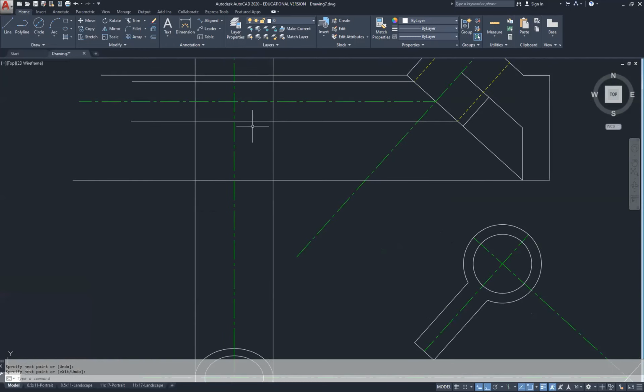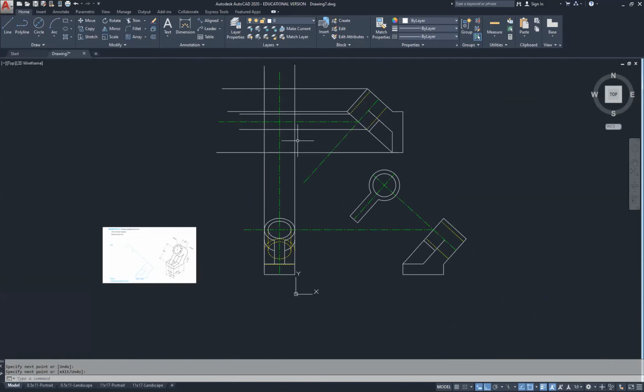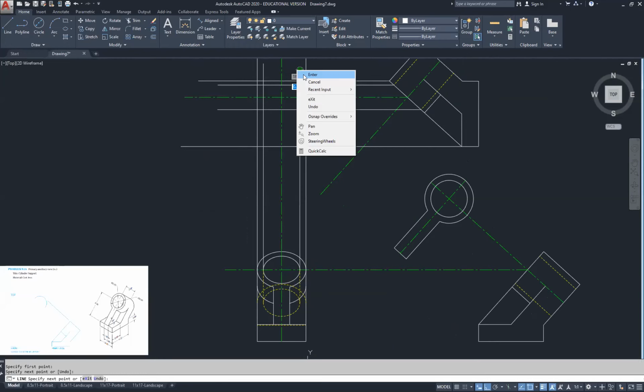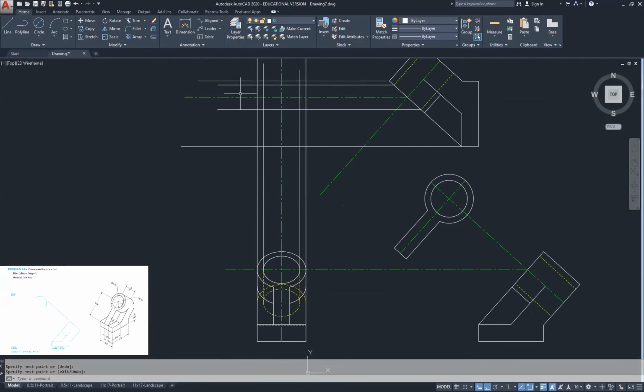So this is that foreshortened view of this circle, visible on the top. And then I'm going to project my line coming across here. And here. You'll notice that I'm not measuring any of this information because this drawing here should be accurate and this drawing here should be accurate. So the information combined from those two views will make my top view accurately by just projecting the lines.